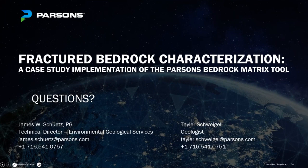So the use of flute liners, which is that sort of sock that unrolls down into the borehole, is the tool we used in between the drilling, the geophysics, the borehole fluid replacement testing, and the well installation. So there's a mitigative tool to reduce the amount of fracture connectivity. And then if you have, let's say, a water supply system at a certain depth, you'd want to avoid interconnecting that. But again, it's a good question, John.